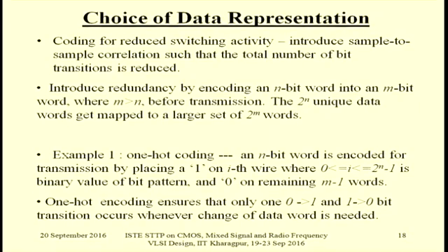Okay, so that means, say, consider n equal to 8. So if n equal to 8, then m equal to 256. Okay, and the value of this can vary from 0 to 255. So when the value is, say, 0101, that means binary 5. So it means that out of the 256 words, only the 5th word will have logic 1. The rest are in logic 0.